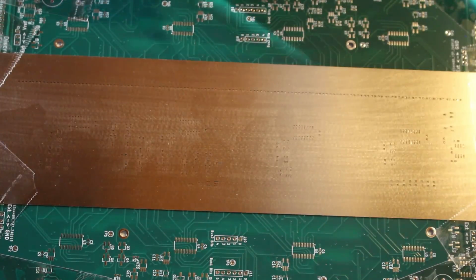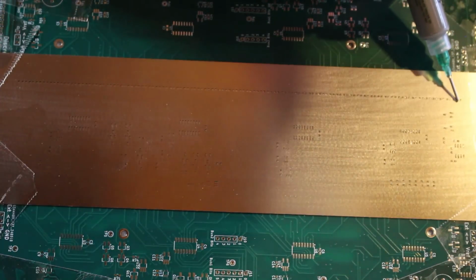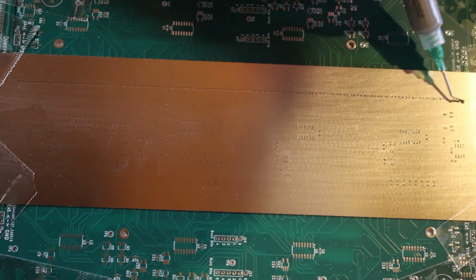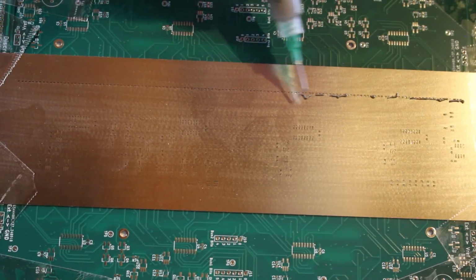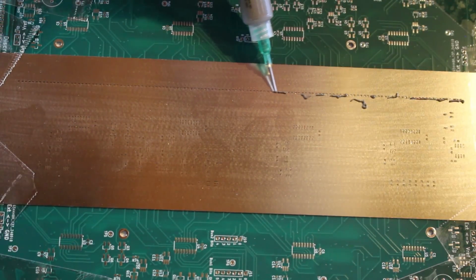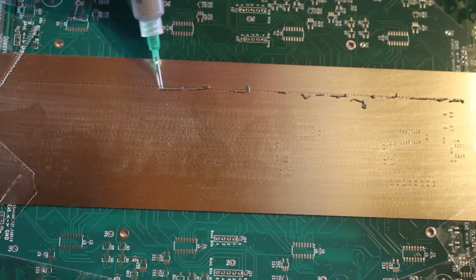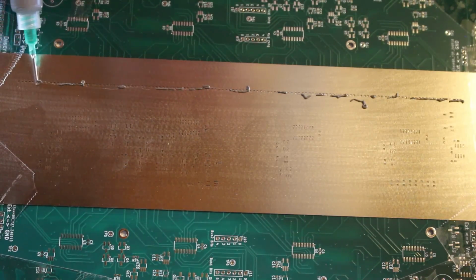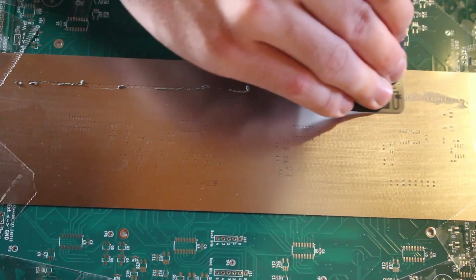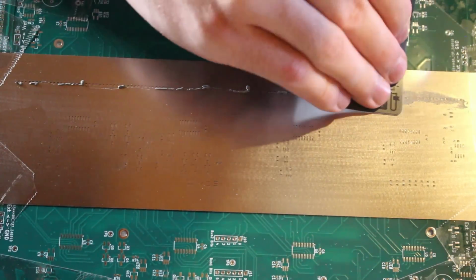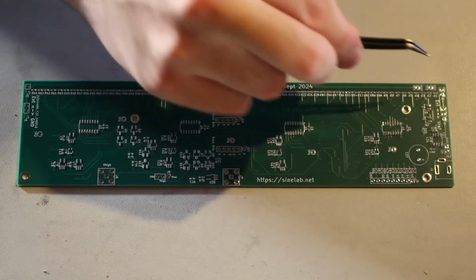I'll put the 6-layer board aside for now, since I will explain its purpose a bit later in the video. To assemble the string DAC, I held it in place with the duplicate PCBs and taped them down. I then aligned the stencil and taped that down as well. Afterwards, I applied a bunch of this solder paste and spread it all out with a gift card. Afterwards, I removed the stencil and started placing down all the components.